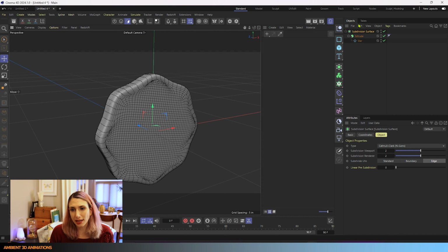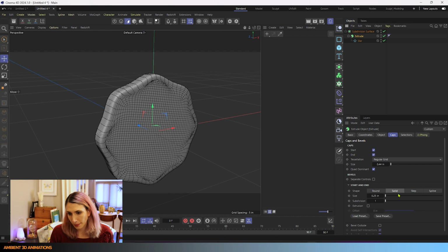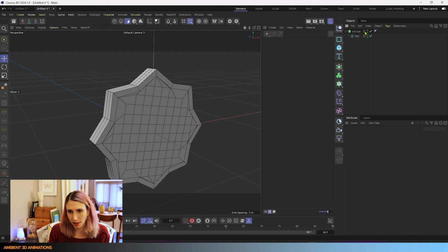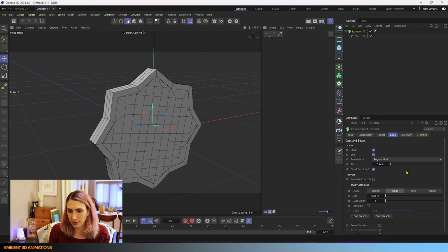So when you add in under solid a bevel, I'll turn this off, you could see that it's adding this edge in here, which is allowing this to create a bevel while in the subdivision surface. The subdivision surface does 2 things. It smooths things out and it subdivides it so that it has more polygons. That's what that does if you're doing subdivision surface modeling. I'm going to delete the subdivision surface.